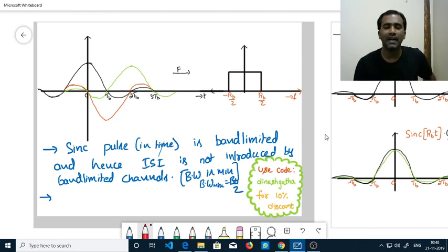So why should we understand the timing here? Since I've drawn a line here, you're able to understand that this is 0 time, this is TB time, because I've clearly plotted. But when you receive the signal, nobody will write the timing. So you have to understand at the receiver what is the 0 time, what is the TB time, the starting time of a bit and ending time of a bit, because only then can you start sampling at certain places.